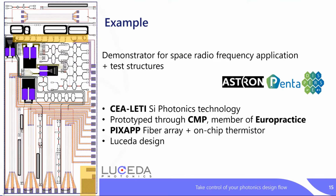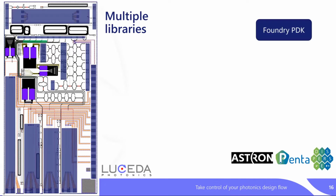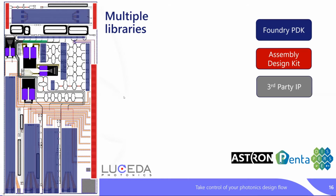Okay, so what design activities are there? I'm taking an example of a chip that Luceda has been designing. It was a demonstrator for space RF applications together with Astron in a research project, and this was done in a foundry technology. If you look at the building blocks that you need, there are multiple libraries involved in this process. There's the foundry PDK, which provides you with, let's say, the fiber couplers, the bond pads, some modulators. There is an assembly design kit, which tells you the rules on how to place your fiber couplers, the bond pads, and so forth. There might be third-party IP, which you insource from a design house.